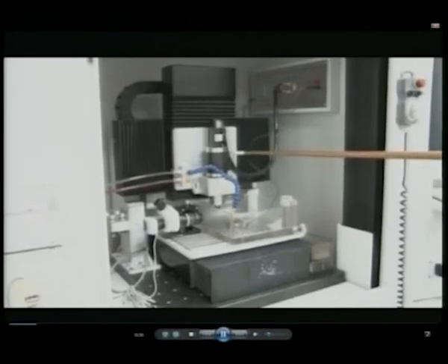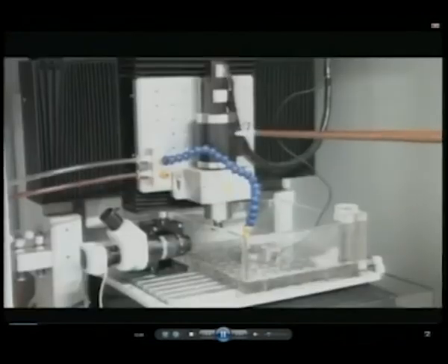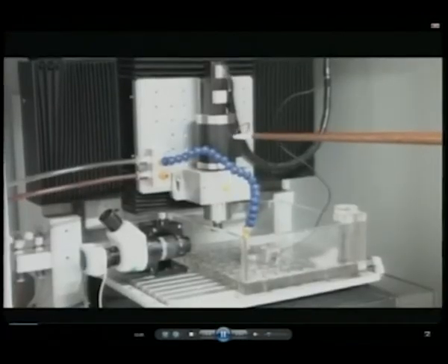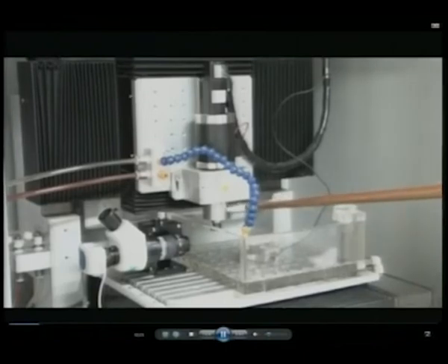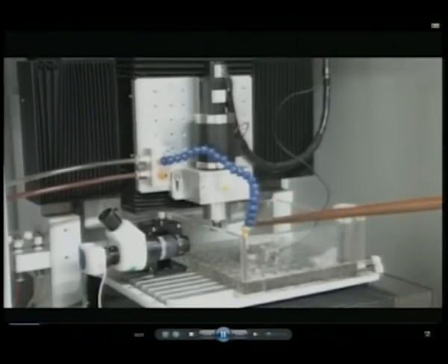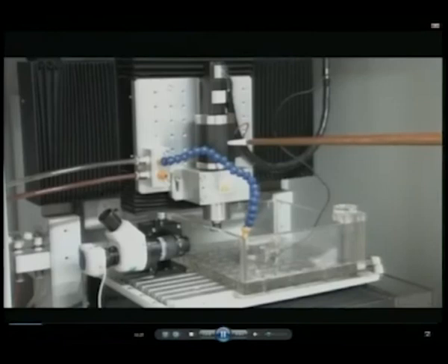The 4th axis of motion is rotational motion. The rotational motion is performed by a servo motor. The servo motor can rotate the spindle either in clockwise direction or anti-clockwise direction. The speed of the spindle can be varied from 1 rpm to 5000 rpm. During EDM process, since one of the electrodes has to be electrically conductive, the spindle is electrically isolated from the machine body.